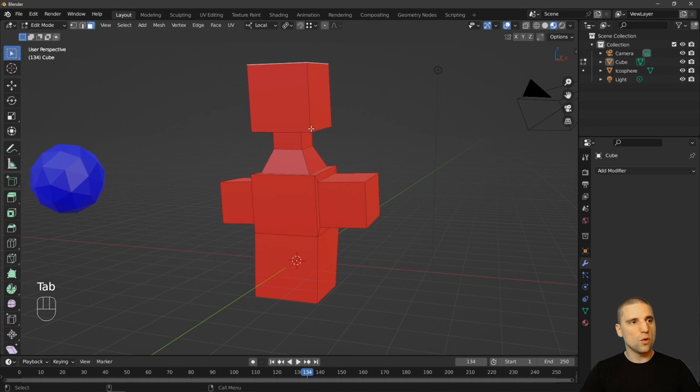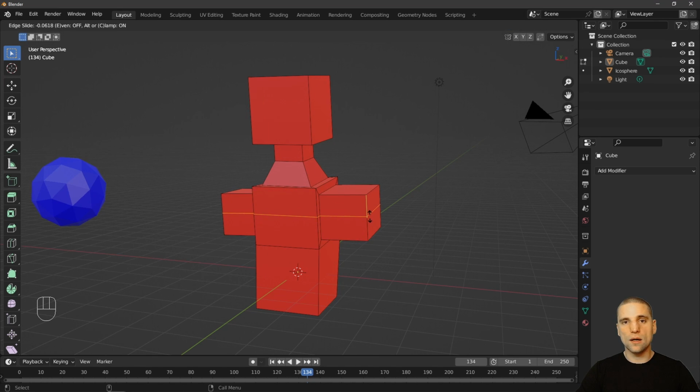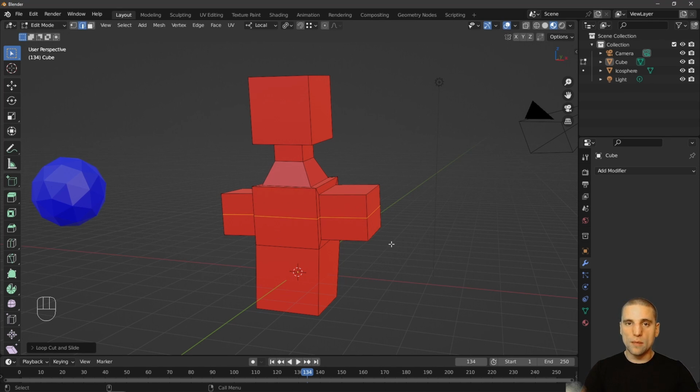Okay, let's go back into edit mode. And so you have a whole bunch of tools here. So we have E and I. E to extrude, I to insert a face, and that combination works really well together. Sometimes you want more definition, and that's Control R, and you can see this yellow line just appears. We're adding a row, and then typically once I have that, I right click, and it sets that row in the very middle of that edge.